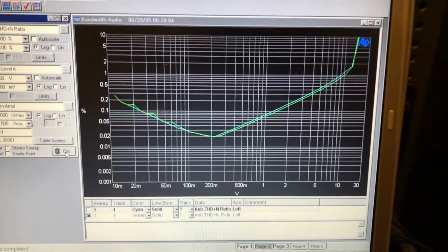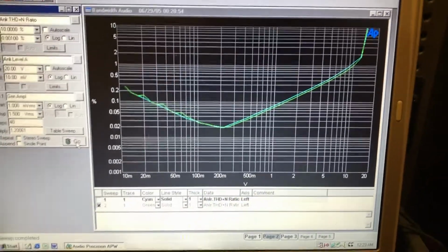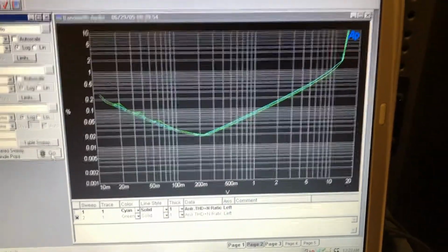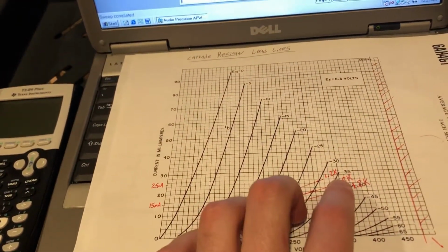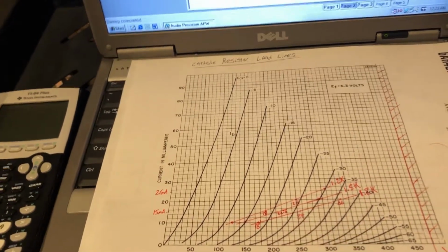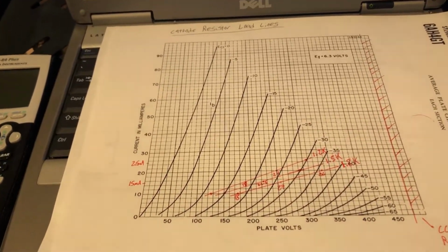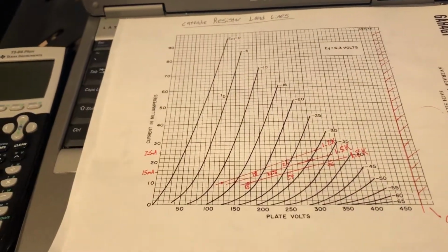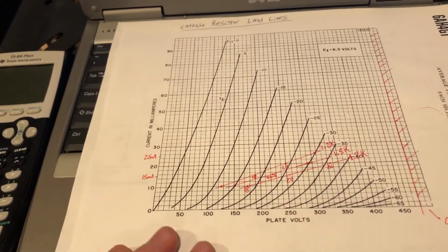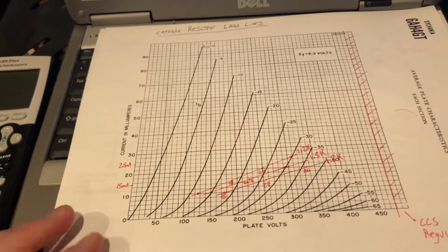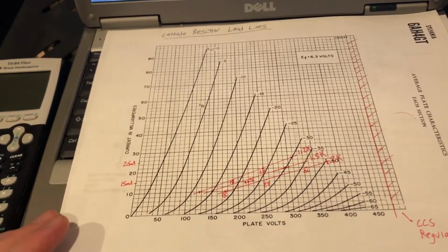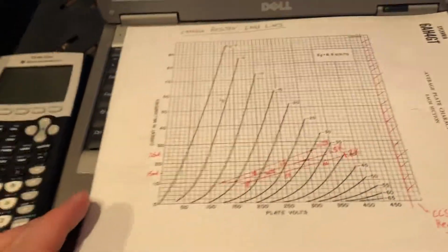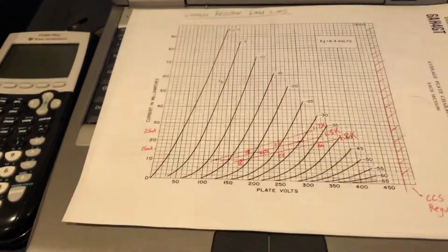So what I'd like to do is come back and test this and move to my second proposed operating point, which would be, again, 20 milliamps, but now use a 1.2 k ohm resistor to recenter and get everything back on center for maximum signal swing. And what I expect is the performance to continue to improve as I increase the current. And that's going to be ultimately sort of a design decision in terms of allowable driver THD versus really the lifespan of the tube, because as I increase the current, I'm dissipating more power in the vacuum tube.